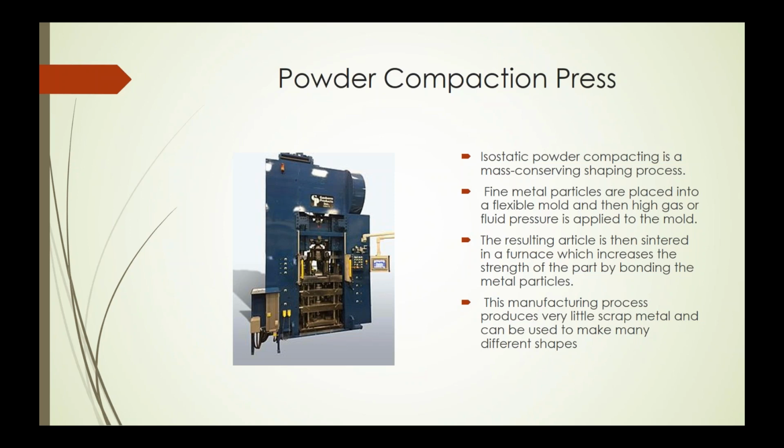So you're making a final product, you're molding it, you're pressing it, you're sintering it in a furnace, which is subsequent to this, and it shrinks during this whole process. But there is a very consistent technique in doing all this. You come out with a really reasonably good part on a consistent basis.